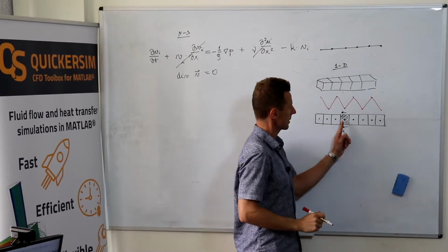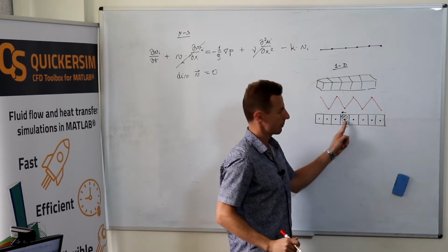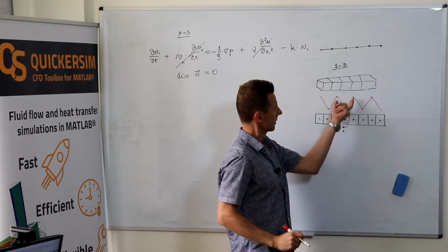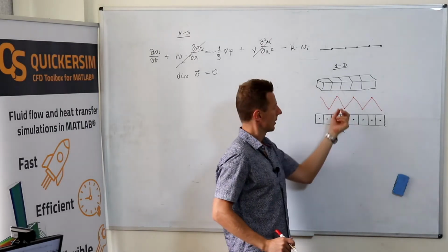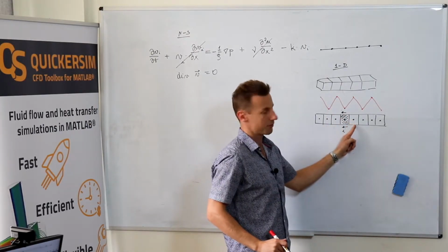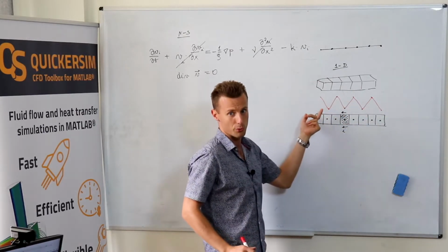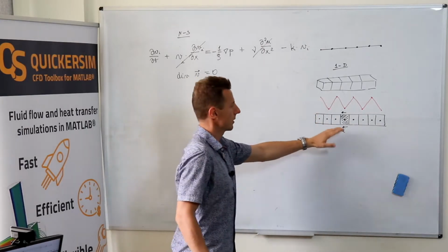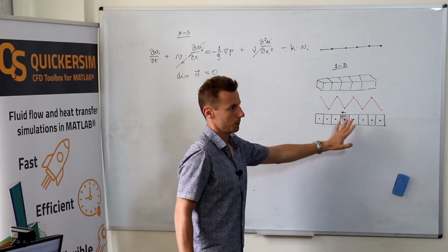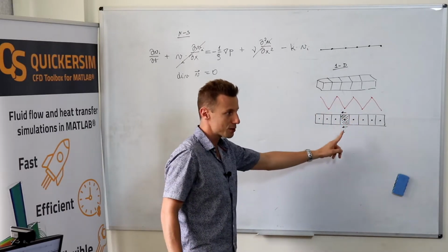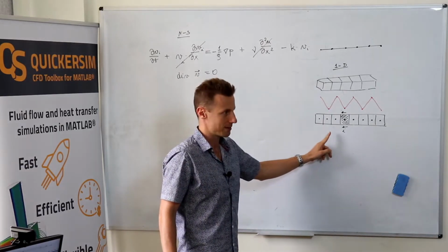Okay, and now see, if we were considering this fluid element, we're taking the pressure difference between that and that cell. What's the gradient? 0. Okay, we're doing it for that one. What's the gradient? 0. And so on and so on. So for each cell, you've got 0 gradient, and you've got no flow acceleration, but a completely stupid pressure field. And this one satisfies your discretization. So that's the real problem.